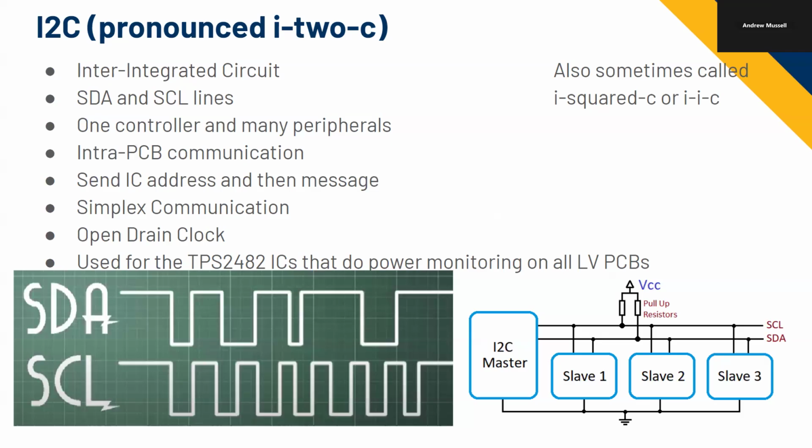So if we increase our frequency, we have to charge and discharge more per second, so it's going to cost more power. But we could talk faster. There is an issue with the open drain that we'll run into, but like I said, we'll talk about that in 2 slides. But yeah, it's basically a trade-off between: do I want to spend more power and talk faster, or am I okay with this data rate and I want to save power?